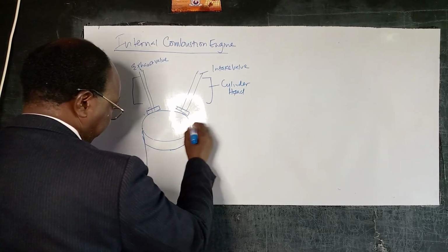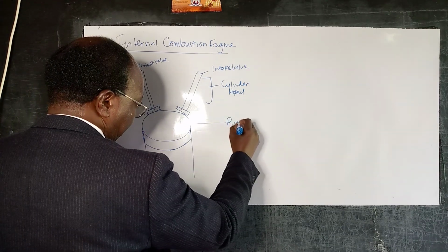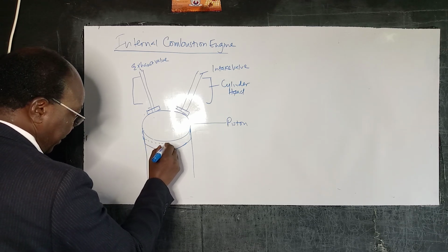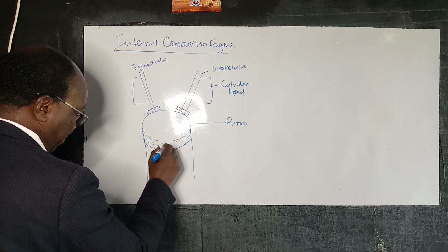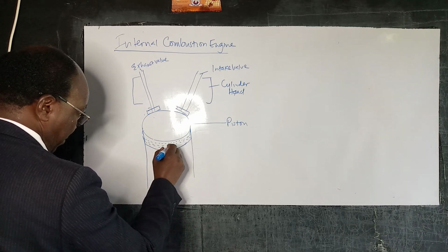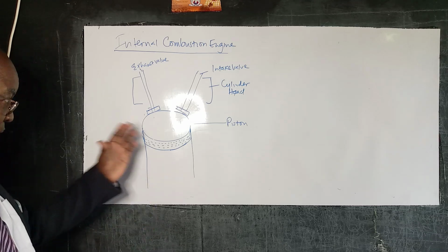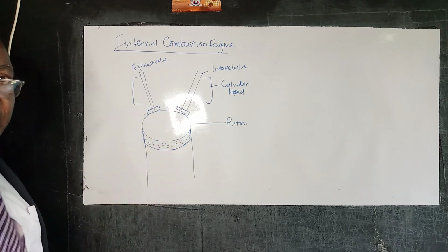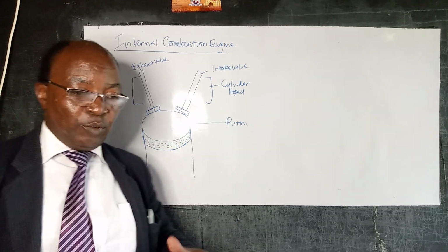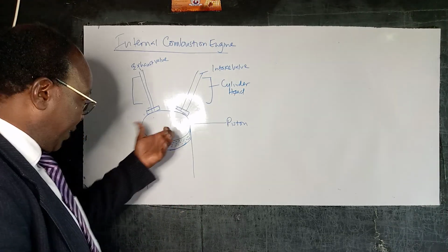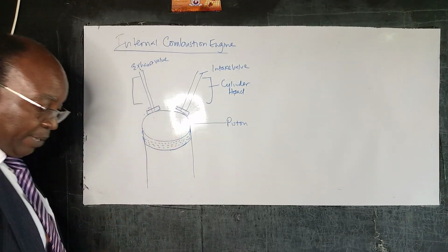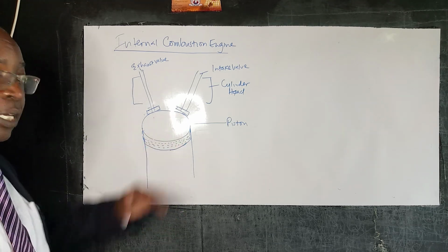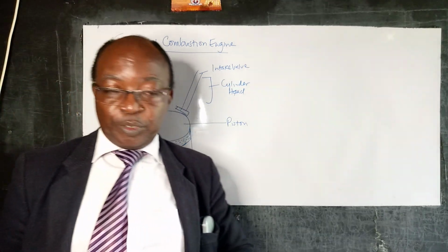So we have our piston, and this piston normally will have rings. These rings are on this piston, and they have to be fitted in the cylinder, so you normally need what's called a ring squeezer to tighten them, and then you are able to push the piston in the cylinder wall, in the cylinder unit, without causing breakages to those particular rings.